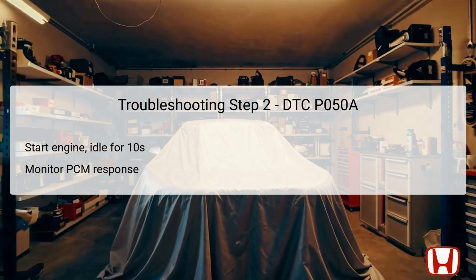If the PCM detects any discrepancies in air intake compared to the target air specifications during this period, it may lead to the triggering of the DTC. Therefore, assessing the PCM's performance during these crucial seconds will provide significant insight into whether the cold start idle air control system is functioning correctly, or if there is a systemic issue requiring further investigation.